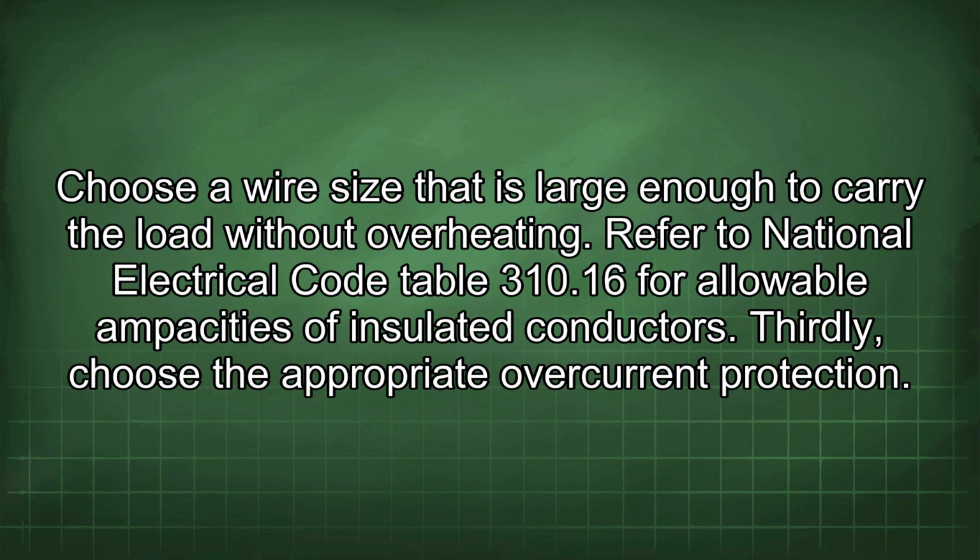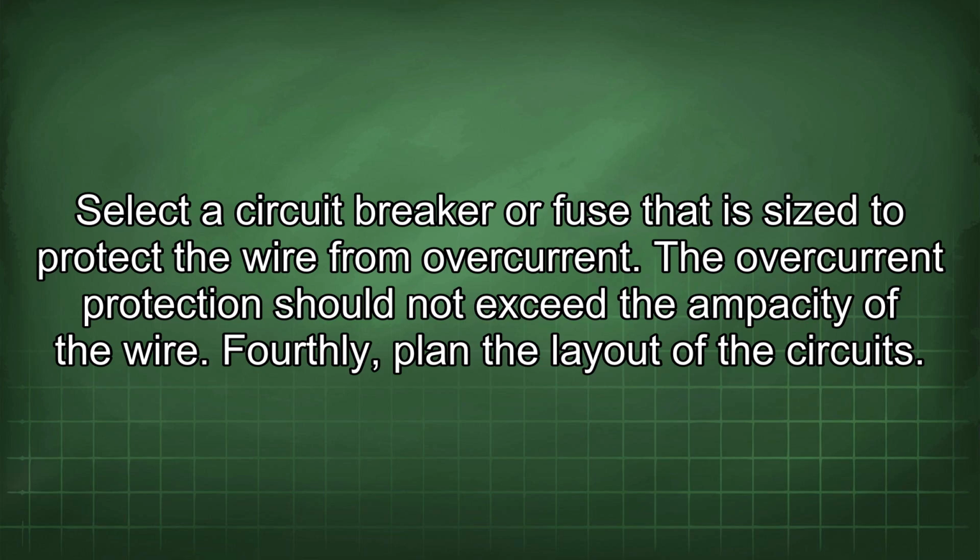Thirdly, choose the appropriate overcurrent protection. Select a circuit breaker or fuse that is sized to protect the wire from overcurrent. The overcurrent protection should not exceed the ampacity of the wire.